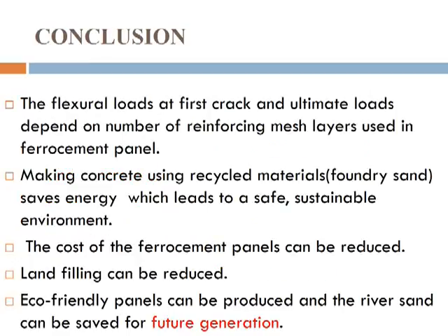Conclusion: flexural loads at the first crack and ultimate load depend on the number of reinforcing mesh layers used in ferrocement. Making concrete using recycled material saves energy, which leads to a safe and sustainable environment. Landfilling can be reduced, eco-friendly panels can be produced, and river sand can be saved for future generations.